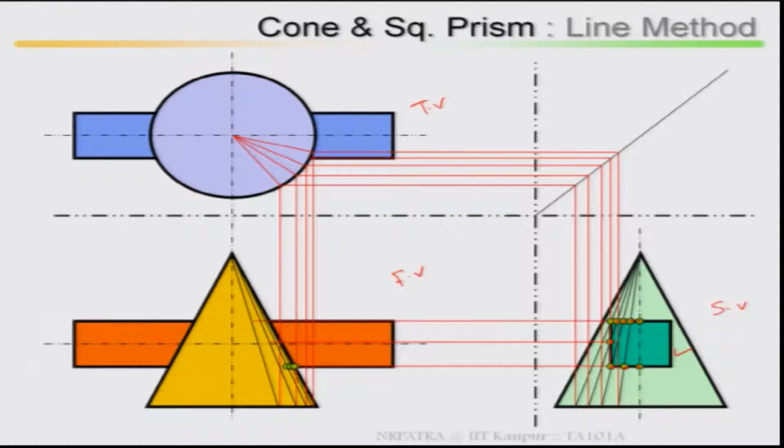From these points take out the external points 1, 2, 3, then where it intersects here, here, from there you project it back on the respective lines. If you look, this line has been projected from here to here, that means from this point you extend it where it cuts, it has to intersect exactly the same line of the cone, you mark it.